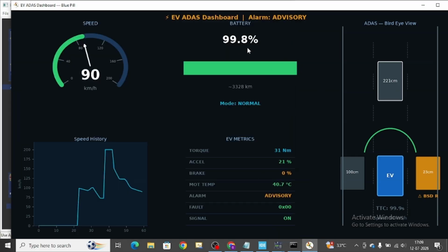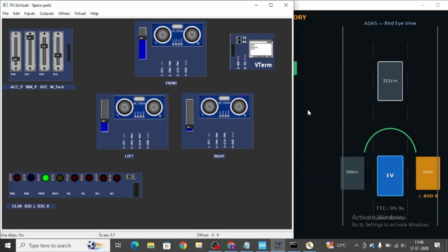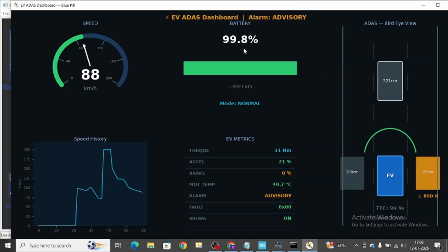We did not see the regenerative braking, right? Just see this. I am increasing my brake pedal. Here it will start charging. Acceleration will be reduced. Here you can see acceleration is very less. My brake is 99%, so it will get charged, but a very small amount of charge is produced, implemented as a 0.1 or 0.05 change. So sometimes it may be shown, and sometimes it may not change.